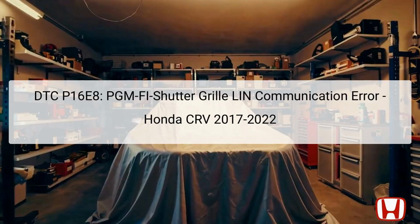The diagnostic trouble code DTC P16E8 indicates a problem with the communication between the Powertrain Control Module (PCM) and the shutter grille's local interconnect network (LIN) system. The shutter grille is a crucial component located at the front of the vehicle, designed to optimize airflow and improve engine efficiency. This grille operates electronically, and any communication error can impede its functionality, potentially affecting engine performance and fuel